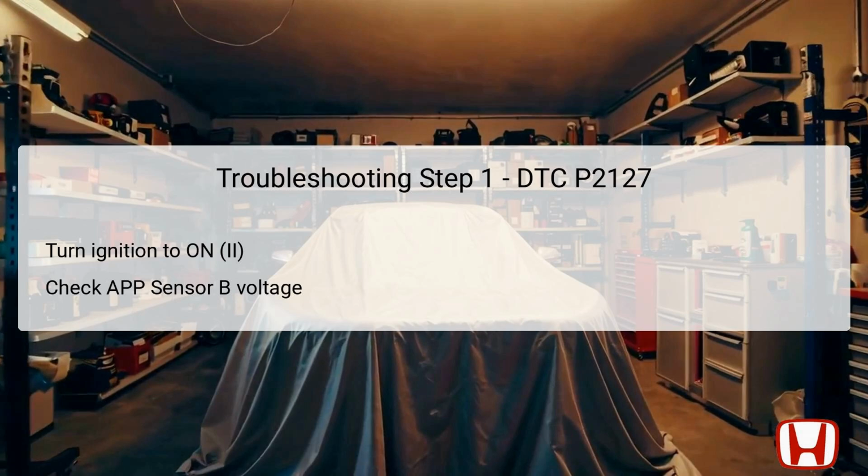According to diagnostic data, if the voltage reads approximately 0.2 volts or less, this indicates a potential fault within the sensor or associated wiring. Should the reading show a higher voltage, it may suggest an intermittent failure, and the technician should proceed to inspect the connections at the APP sensor and the ECM/PCM for poor connections or loose terminals. This initial step is crucial as it helps in identifying whether the system is functioning normally or if further investigation is needed based on the voltage readings observed.